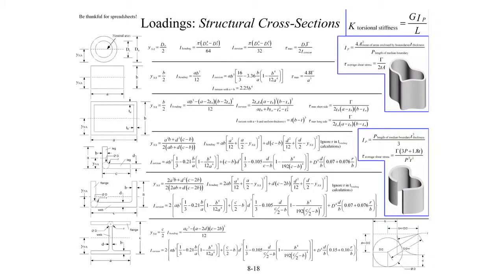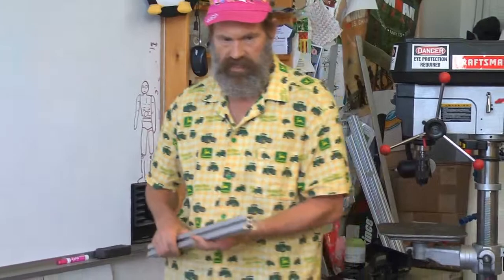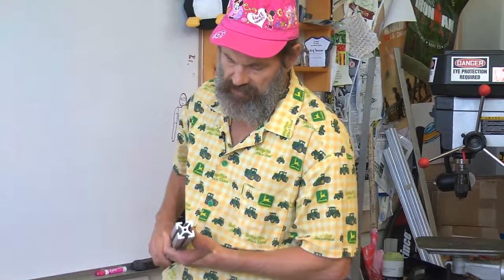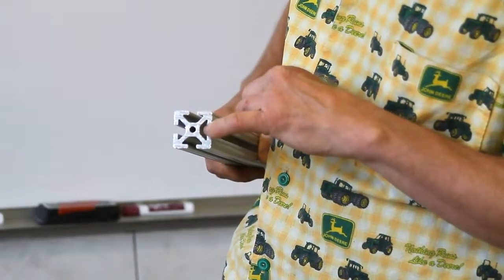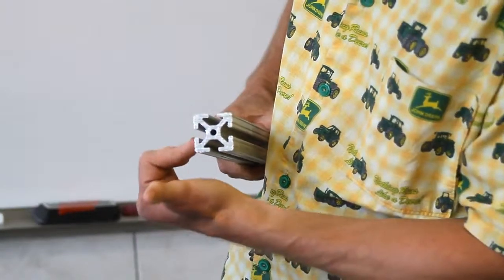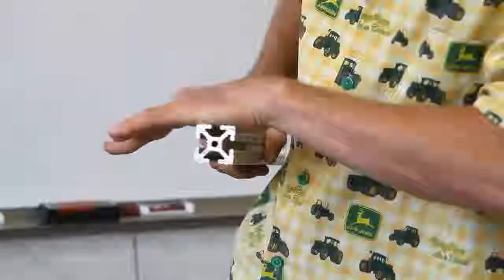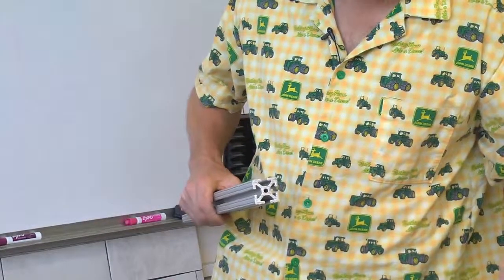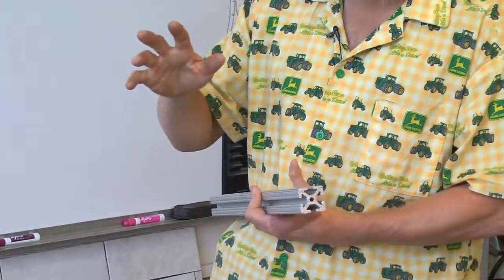Remember, you're designing your machine typically not just to last for a day or a week, but for years. Coming back to the stiffness question on detail, you can look at something like some of this modular aluminum structure, which is really handy, and it goes by a bunch of different trade names. It's wonderful because you see these dovetail structures in the sides that allow you to bolt stuff to it, and like a modular kit, you can very easily build up very complex machine frames out of this stuff.